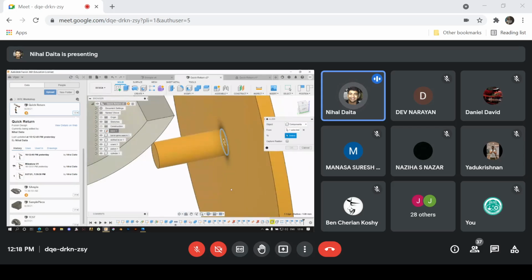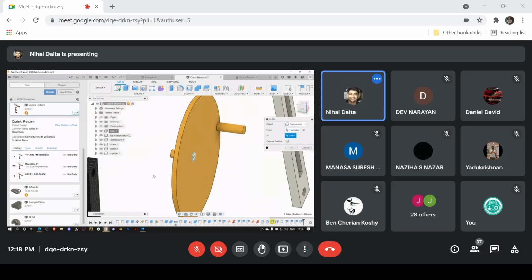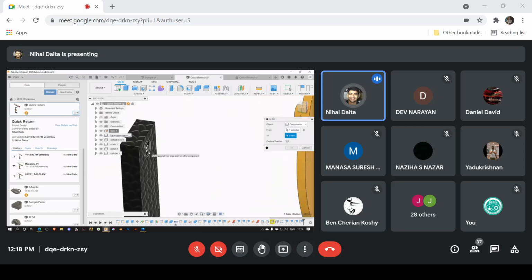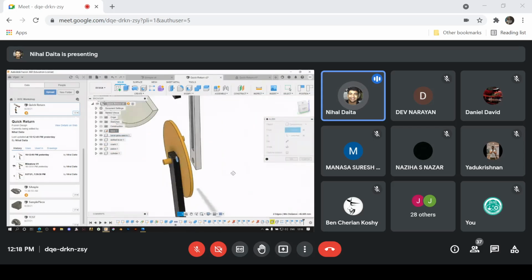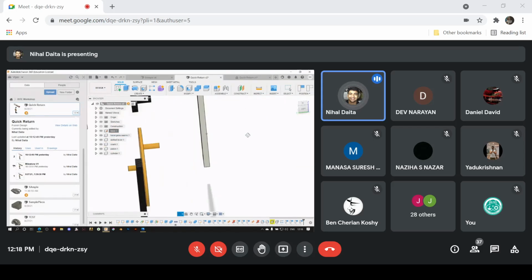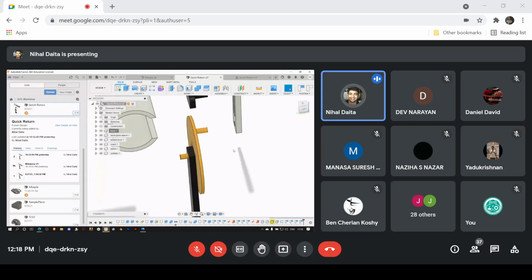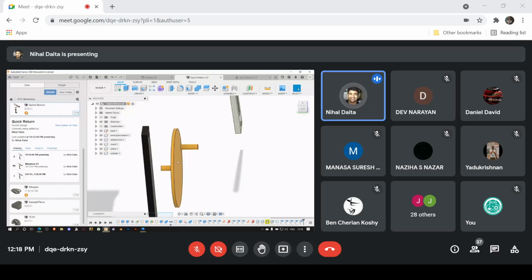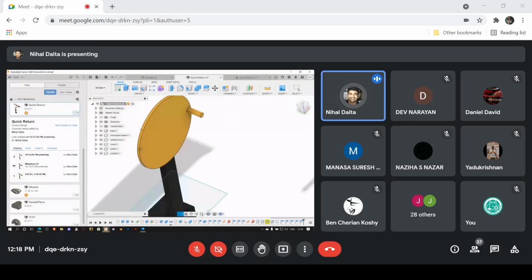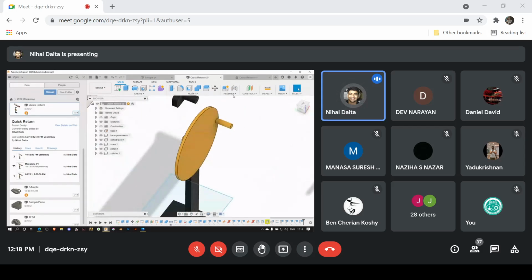So I choose the circle here. And I choose the circle here. And as you can see, it's snapped onto there. The thing to notice, the position is not fixed, okay? If I click revert, it will just go back. So I'll just capture position. And now if I move it about, it will still move away. I can revert it back. Now if I give the joint, right, or the constraint, it will be able to stick there.